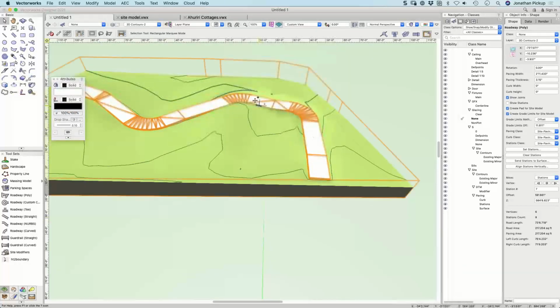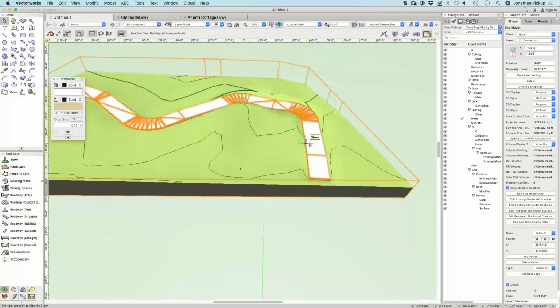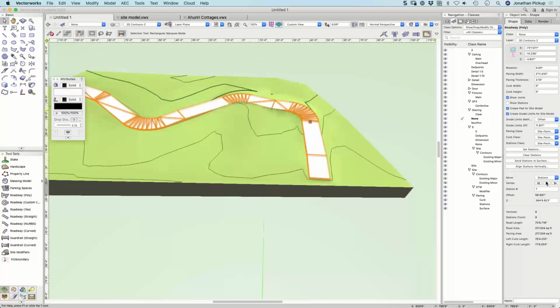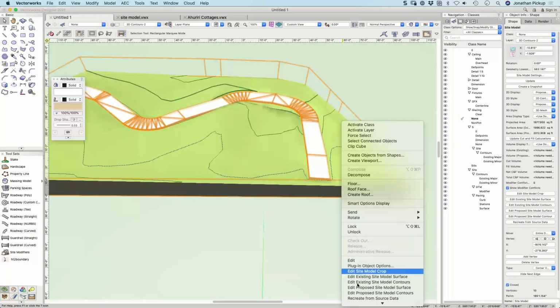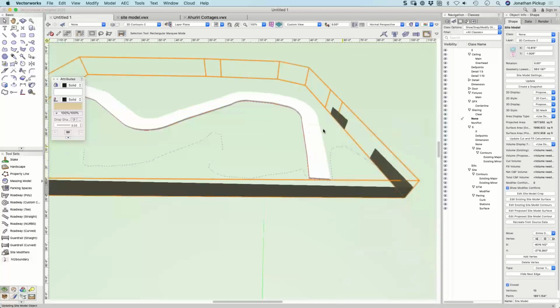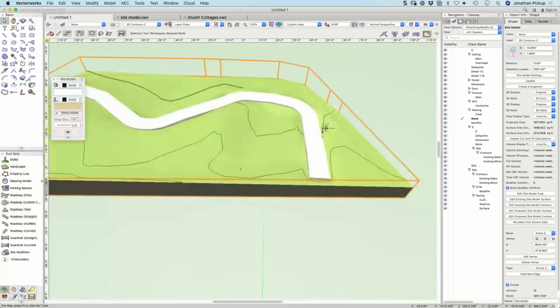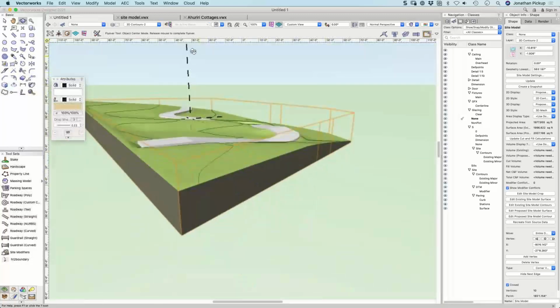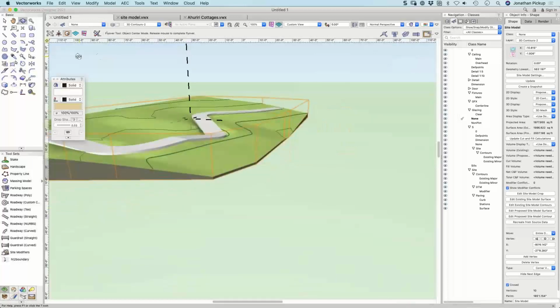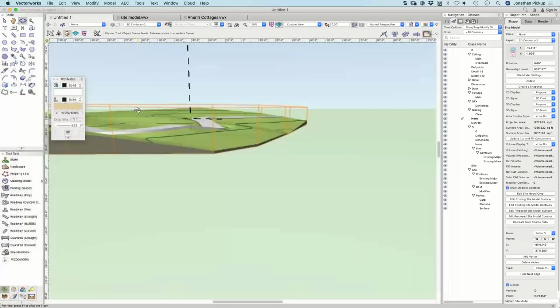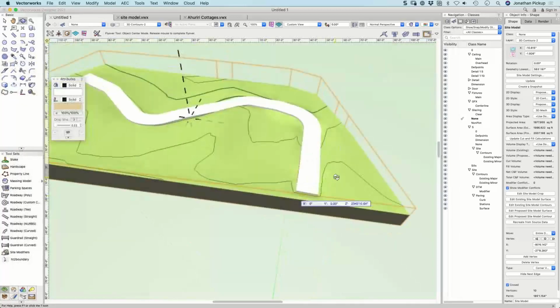So if I lift the elevation of these ones, let's select that again. Let's go back to my back. So let's make that one plus 18. That should make it above the site. And let's update my site model. And that should have filled up that area underneath. So you can just do spot or station by station, and you can make them fill or cut.